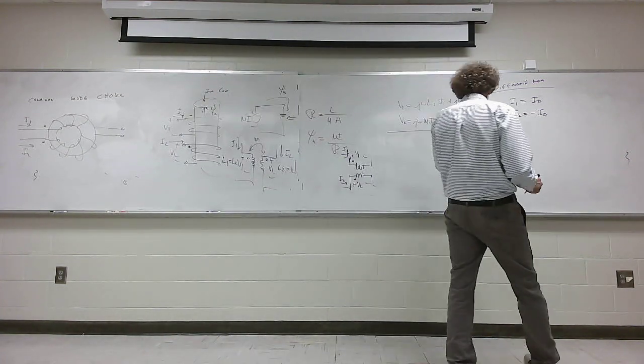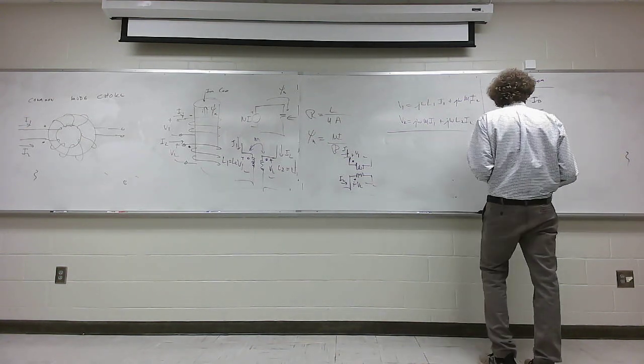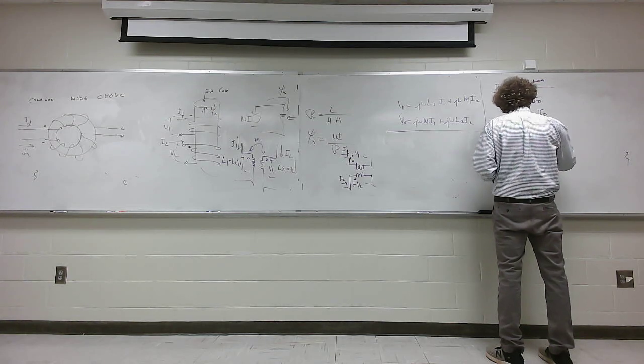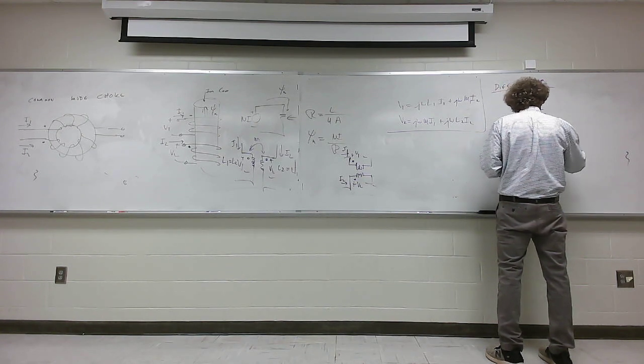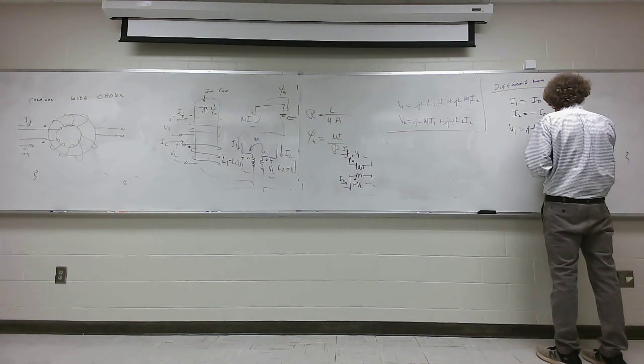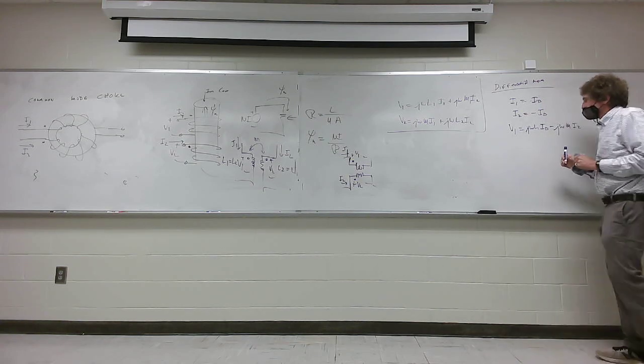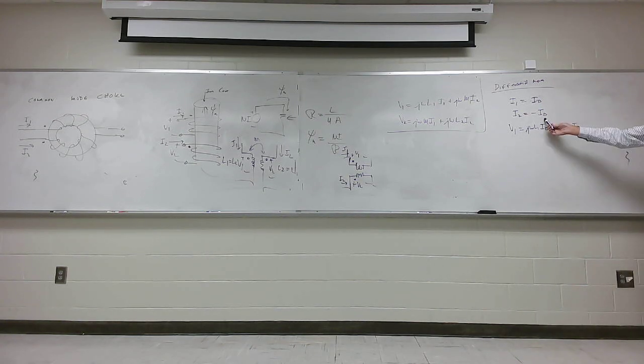And I look at this, I1 equals minus I2, which is I differential. When we look at V1, that's equal to j omega L1 times I differential, and then it's going to be minus j omega M I2. Now here's why: that I2 is going to be the same magnitude, opposite direction, so the negative sign right here denotes that. Y'all follow me on that, guys? How many understand that? I'm not going to spend a lot of time on this if I don't have to.